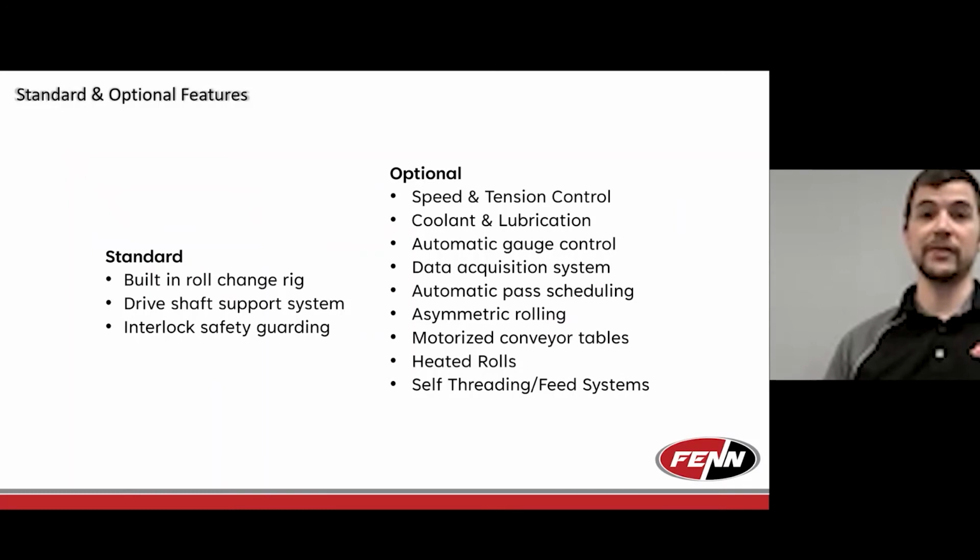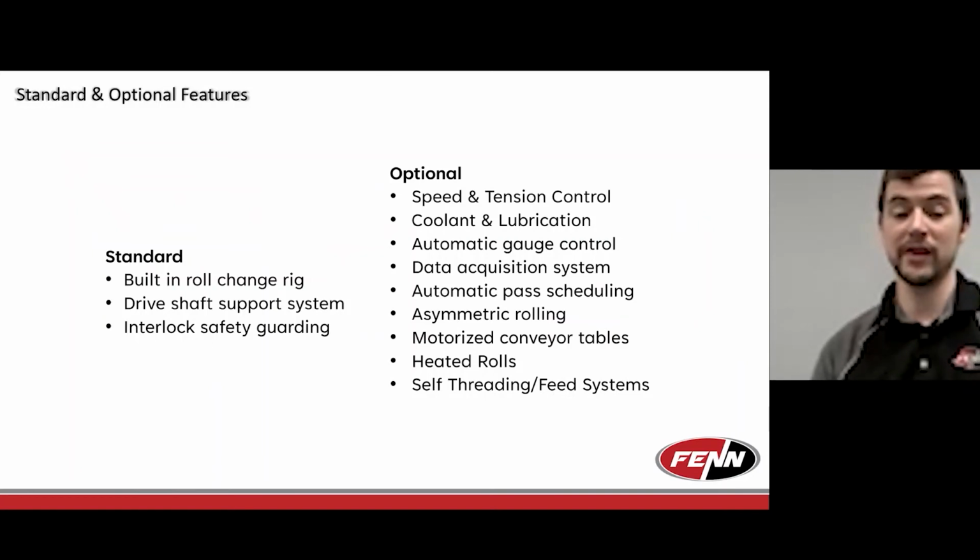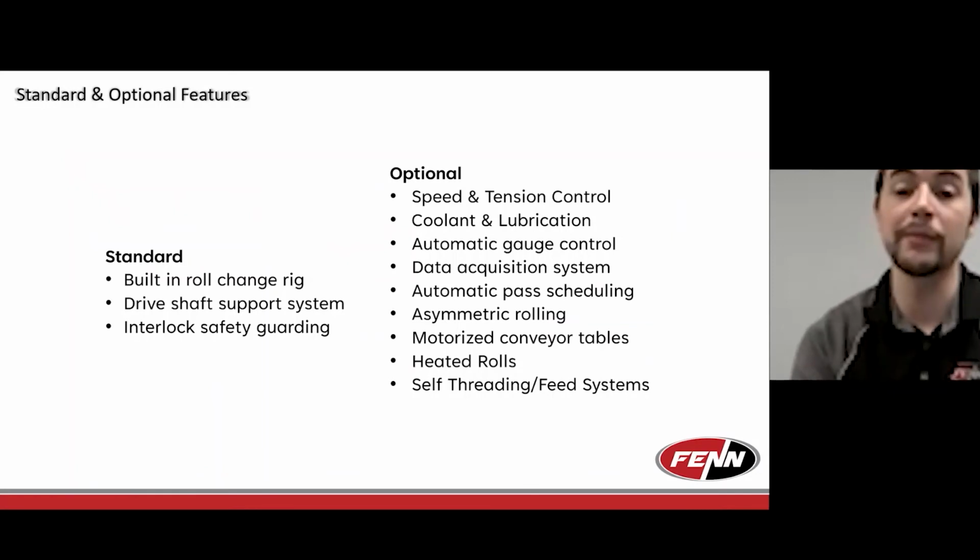One is general collecting of data for assessment and experimentation, and the other is used by customers who have been running production batches, and when something goes wrong in the batch, they can go back and look through the data and see if there's anything the machine picked up, either through the load cells, the motor torque, or any of the settings, that was atypical, in order to help them assess the root cause of where the problems occurred. So a data acquisition system is extremely commonly used in mills, and when it comes to laboratory mills, it's pretty much a standard feature that we provide at this point, but it's not provided on everything, which is why it's listed as optional.